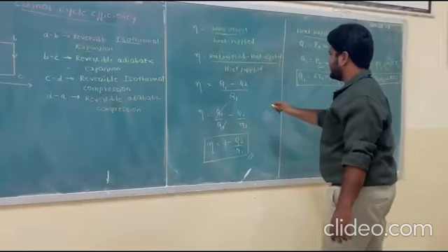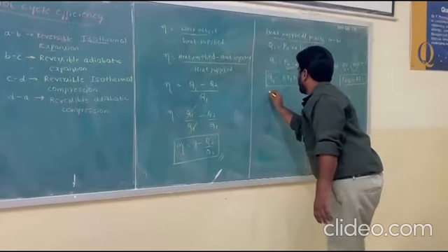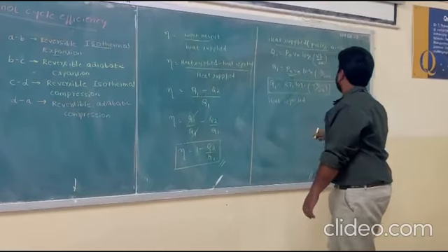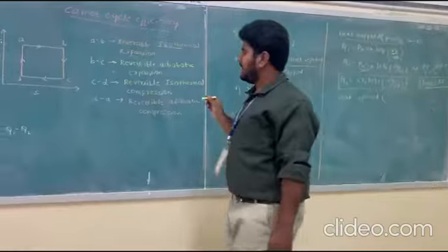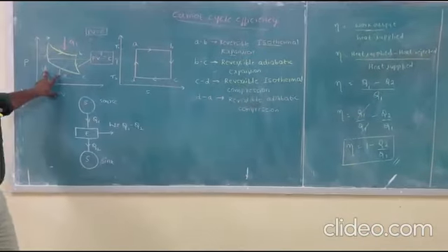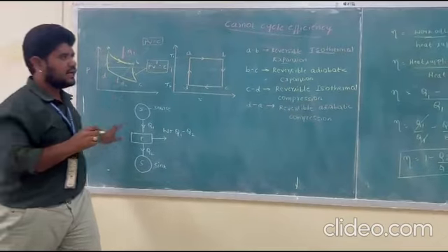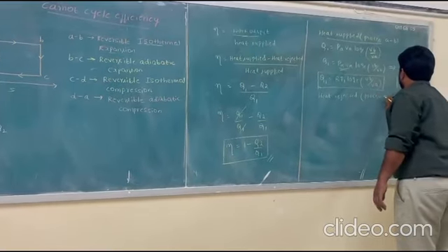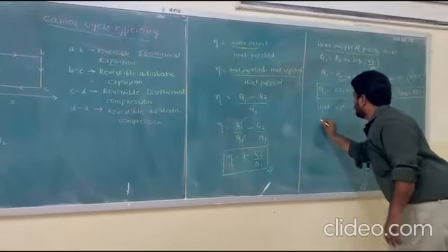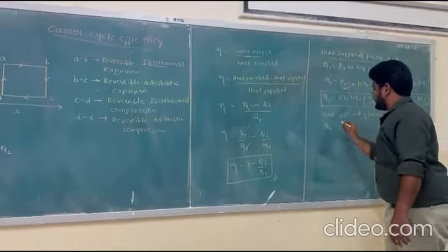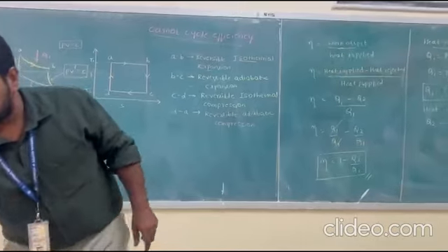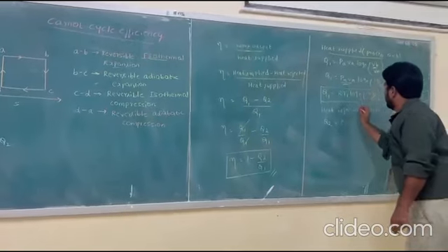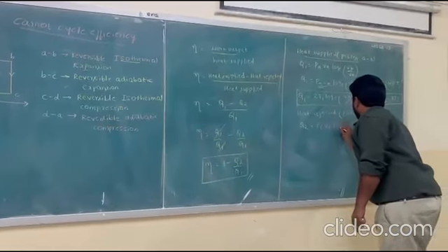Now I should go for the heat rejected, Q2. So now I consider heat rejected. The heat rejection process takes place between C and D. So for process C to D, same formula: Q2 is equal to, starting from C, PC VC log e of the volume ratio.